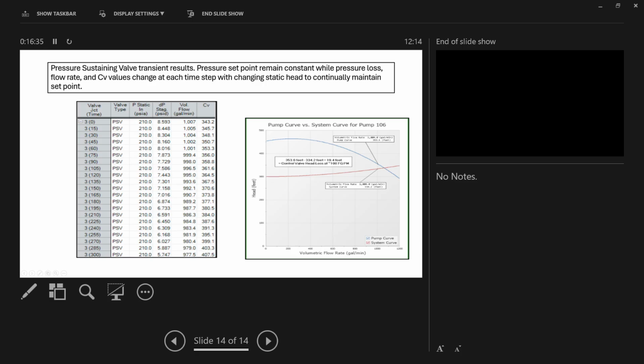You see initial flow was high due to restriction. With the isolation valve or whatever it may be, it was too much, but if you provide a control valve, it will be slightly less. And it will go on changing the CV value also. So when you are changing the CV value, your flow change will gradually minimize. The valve pressure differential also minimizes. Initially it was high. Gradually, when you are opening the control valve, the CV value also opens and your pressure drop will also minimize.